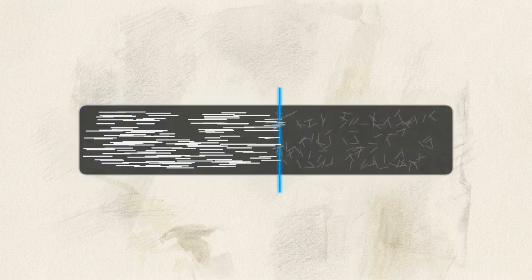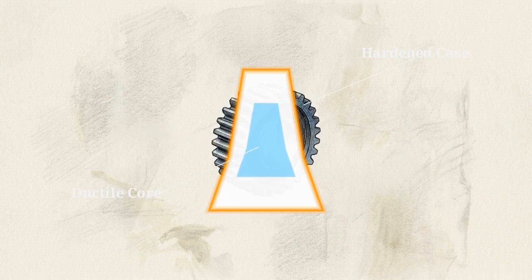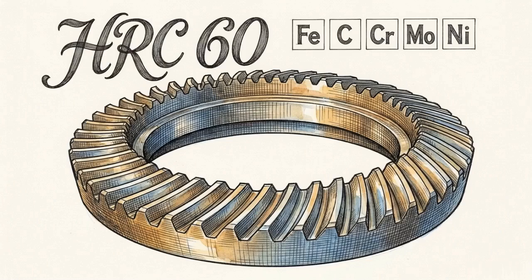Specialized forging processes are used to perfectly align the grain structure of the steel axle shafts, maximizing their resistance to twisting forces. Heat treatment processes, specifically induction hardening, are applied to the gears. This creates an incredibly hard exterior case to resist continuous wear, while leaving the internal core of the steel ductile enough to absorb sudden shock loads without shattering. Brilliant geometric design only survives the realities of continuous commercial hauling when executed with exacting material science and targeted metallurgy.